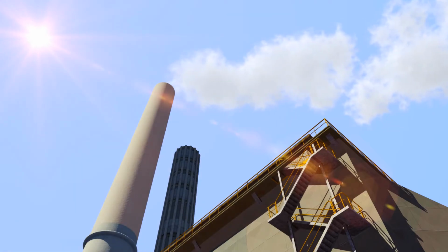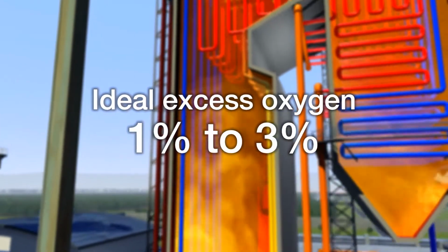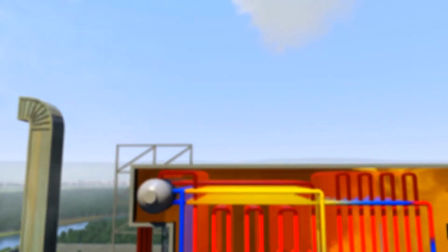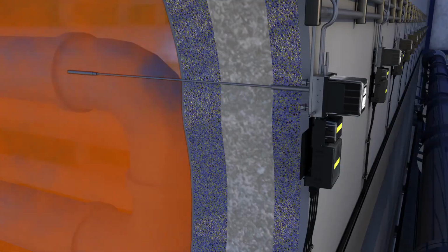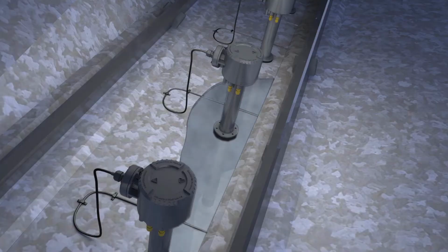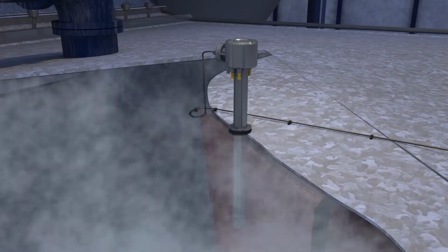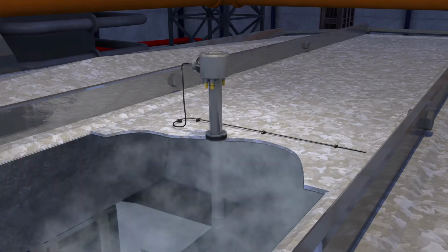An ideal figure for excess oxygen is between 1 and 3%, depending on a range of factors, including the fuel being combusted, the steam load, and the condition of the boiler burner. One way of striking the right balance is by continuously monitoring levels of oxygen at key points in the combustion exhaust gas stream. By using a combustion analyzer to measure the amount of oxygen remaining after the combustion process, it's possible to fine-tune the air-to-fuel mix to help optimise efficiency.